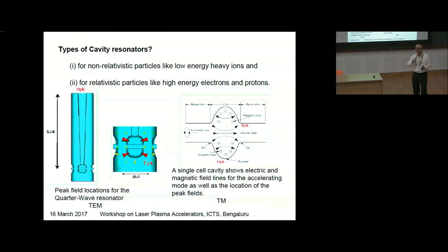That means some kind of electromagnetic mode, oscillations, will be set up inside the cavity, where a half wave or a full wave can be sustained. A standing wave can be generated. A standing wave of electromagnetic nature of different types: transverse electromagnetic, transverse electric, or transverse magnetic modes are set up. Different modes are set up.